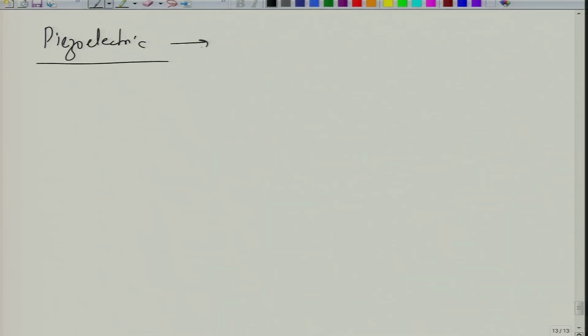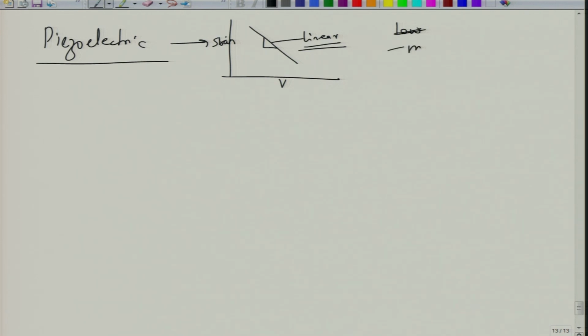One thing which I forgot to mention is that when you make piezoelectric measurements, you have to ensure that you are measuring the slope of basically the strain versus voltage, let us say, or the charge versus the force. Basically, the measurement should be made in the linear region, right. So, linear region requires that the measurement is made at smaller voltages or smaller forces, otherwise if you go to nonlinear region, then the measurement may be wrong.